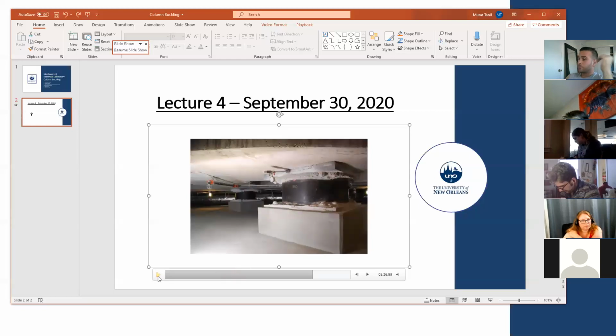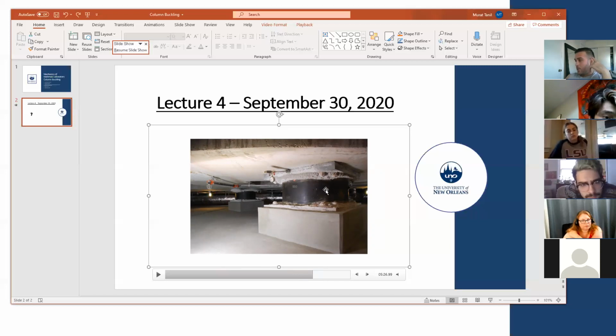This is the example. If you look at the screen, you will see the real life example of the translation free, rotation fixed connection. So this is the seismic footing design. This allows your columns or your footings to translate on the XZ plane, but it restricts rotation. You don't want your structure to be overturned, right?